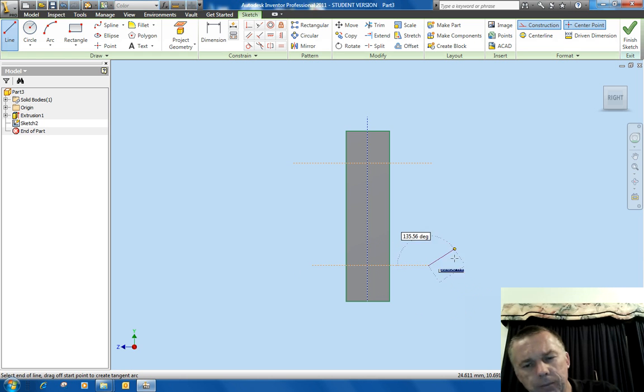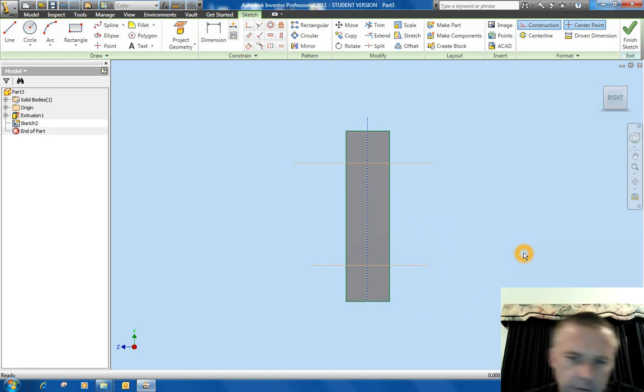To turn, see how line's still connected, I just press escape and it turns that line off, for want of a better word. Now you might think, well, why is he bothered going to like something that looks like a hidden detail line? It's actually a construction line. The construction line is necessary to use to get my positions right, and then I can put my circle in. So I'm going to turn construction line off now. I clicked up there again and just turned it off.